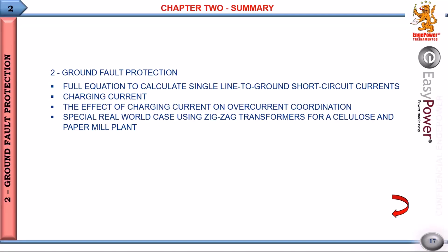And we see by the digital fault recorders that many motors burn because of harmonics. And the most dangerous for overheating are the negative sequence harmonics, the 5th, 11th, that have magnitudes that are more relevant. Okay?